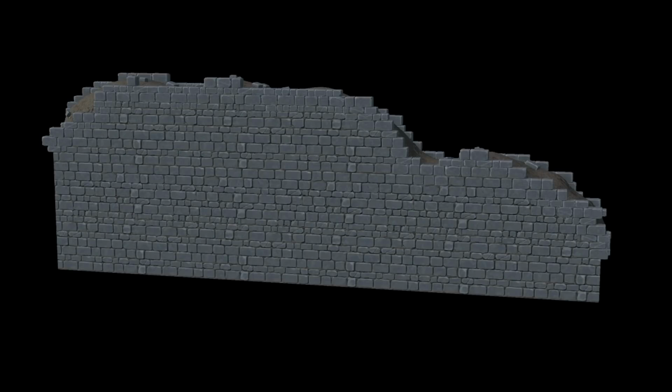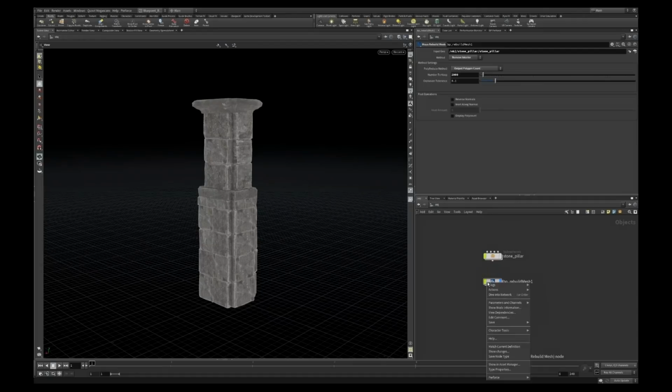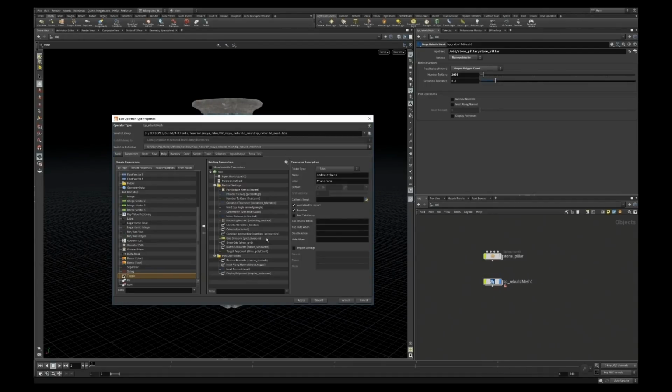Okay. One of the powers of Houdini is the Houdini Engine and making all of these tools way more accessible to your artists. One of the struggles that I ran into is none of my artists want to use the Houdini Engine in Maya. They don't like the attribute editor interface. One of the problems they ran into was there's no tooltips, and the layout that you've made doesn't line up with what you have actually created in the type properties for your HDA. It's just in this big vertical layout, and hidden parameters don't work, and yeah. So what I ended up doing was creating a wrapper for the Houdini Engine plugin.